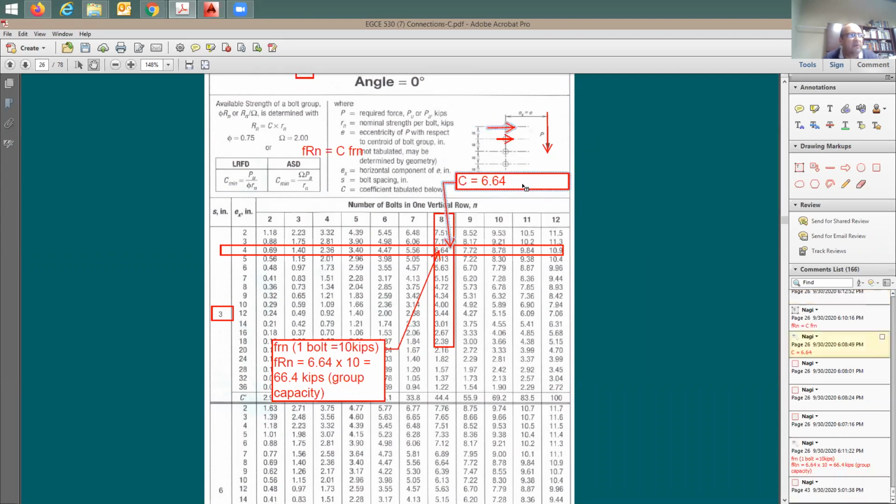And other forces also, if I may take this down here. Another force is going to be coming like this, and another force is going to be coming this way. They have been considered. They accounted for it when they give here this reduced number of bolts. This reduced number of bolts, equivalent number of bolts, considers the effect of the eccentricity. They made it in a different way.